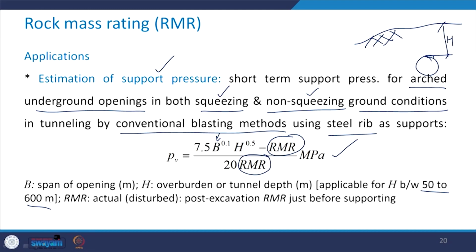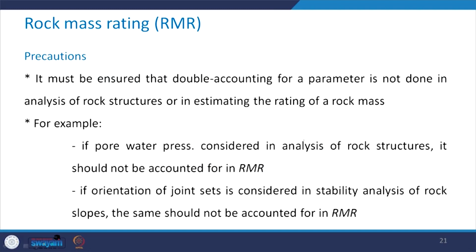Take a note of it that the RMR which you use here should be the actual one, that is the post excavation RMR just before the supporting. That value you should substitute here in this expression.